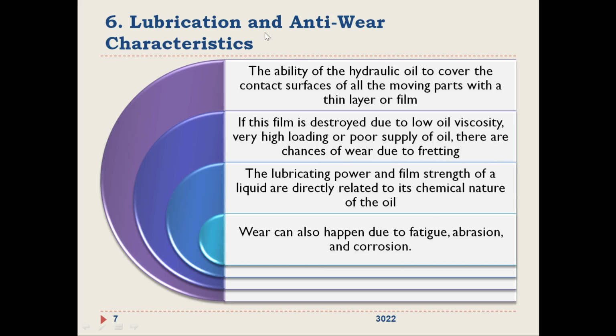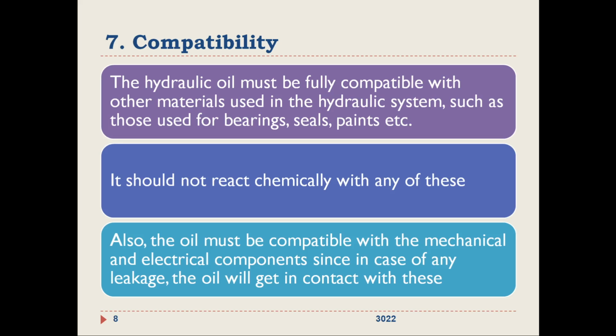So along with the lubrication, another property mentioned here is anti-wear characteristics. Wear can happen not only due to friction, but also due to fatigue, abrasion, as well as corrosion. All these should be avoided with the use of proper hydraulic oil. Compatibility, which is the seventh property.